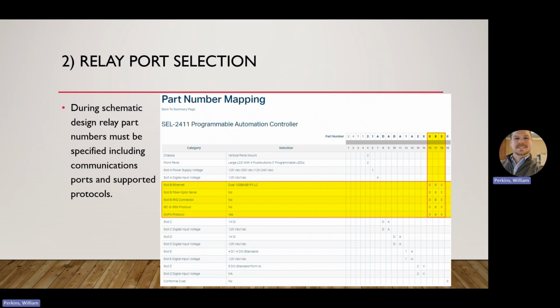And in newer substations, instead of having DNP3 protocol, you could have what's called IEC 61850. This is a more recent protocol that's been developed specifically for communications over a network or local area network. Again, this is just a quick example of how the A&I group would interface with the PNC group in the design.